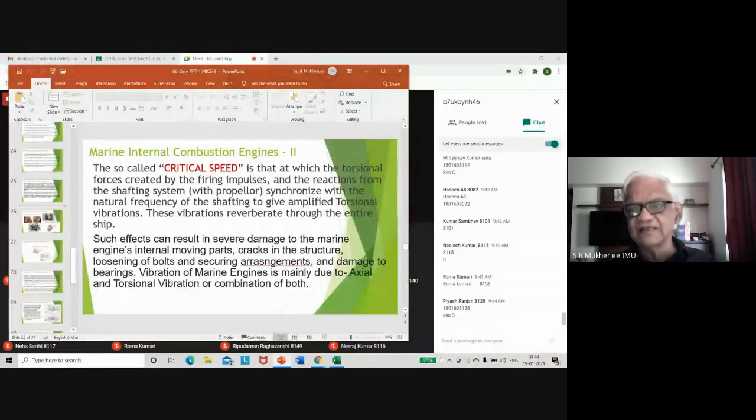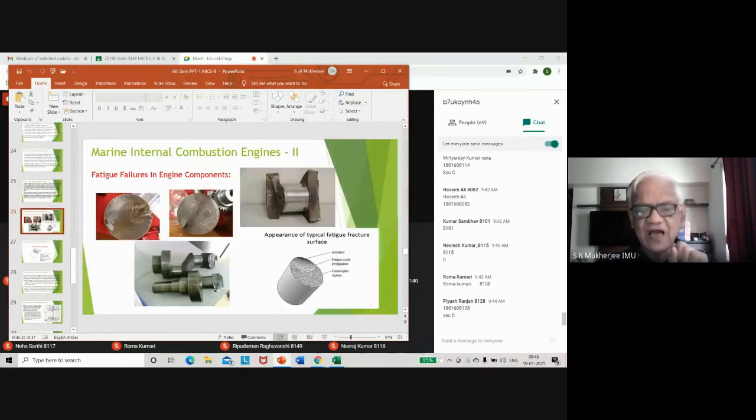Okay, I think this is reasonably easy to understand. So let's have a look at how fatigue failure, this is plate 26, how fatigue failure takes place. Now, if this critical speed was made continuous, the shaft will definitely fail. The extent of vibration, that means the twisting of the shaft, will cause the shaft failure. No matter how strong the shaft is, it is going to fail.